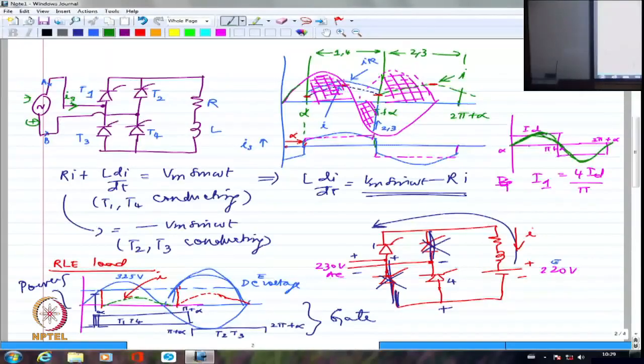Because this is essentially pushing the current behind. That angle is telling you how much the fundamental current is being pushed behind. So if the current is being pushed behind this way, when I calculate the power, generally we say V times I integrated over a cycle and averaged over the complete cycle. So obviously, wherever the voltage and current are not in phase, I am going to have some reactive power. That's what manifests itself as reactive power.